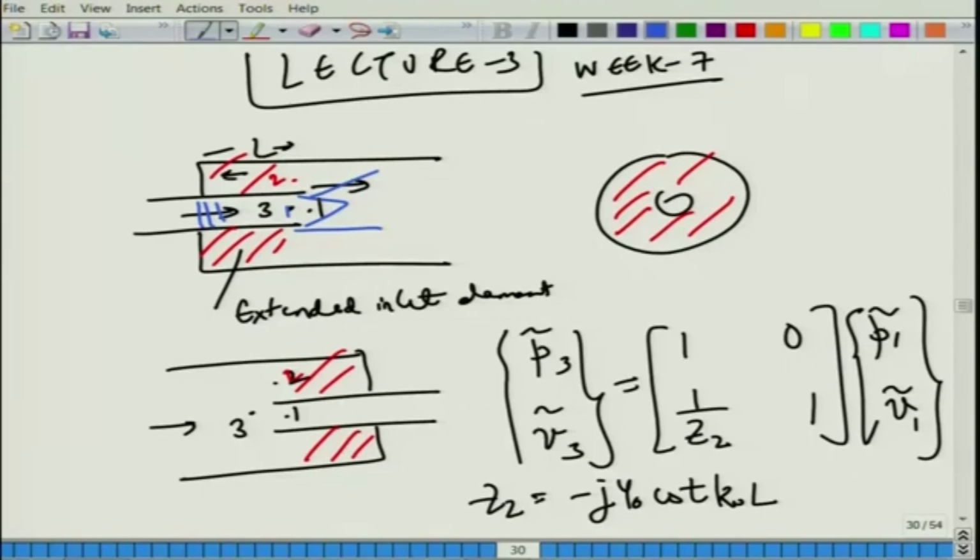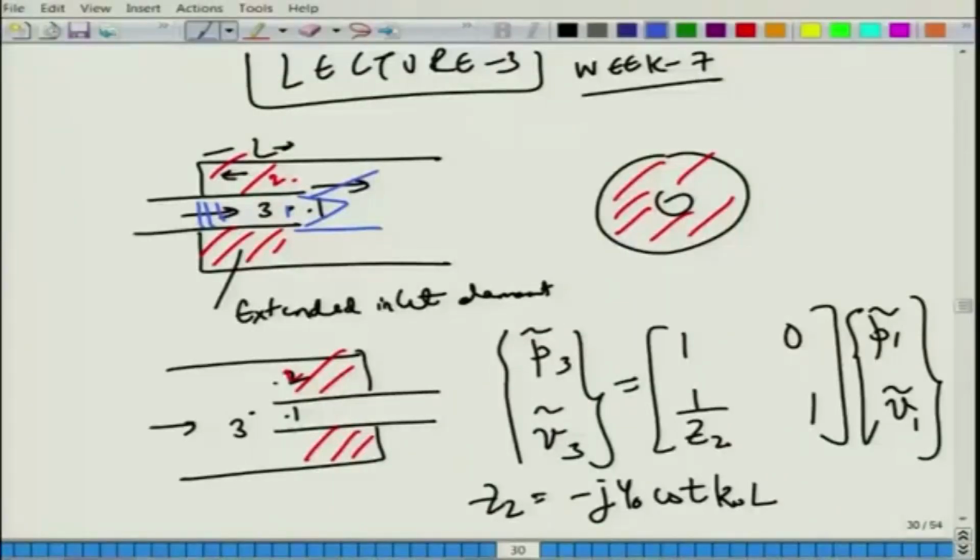You connect it by a perforated bridge, just as I mentioned at the beginning of the last lecture. Nevertheless, for the sake of completeness of this theoretical development and what has classically been taught, we do consider some loss factors. They are related to the head loss when the flow expands suddenly from a pipe, and that would, like I said, aid in the attenuation.